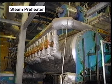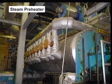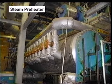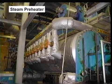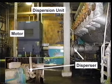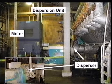And then these lines right here, as you can tell, is steam. The steam is added here, and in this case it's 35-pound steam. The 35-pound steam is added across this heating zone, and good agitation will heat up the pulp and soften the contaminants. Okay, so here's that heating zone.